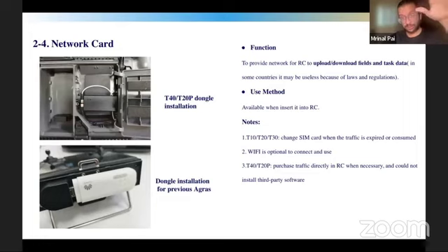It can also be connected to the internet, right? You can have a dongle installed directly in the remote controller itself. You can have multiple drones in a fleet. For example, this is useful where, as a spray service provider, I have say 5 drones, or 20 drones, and every day these drones are being used, and you want to monitor how many acres they have sprayed or not sprayed. So having connectivity also helps give central command and control if required for such operators and service providers.